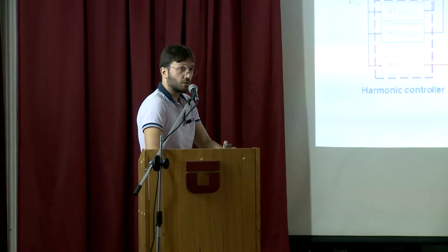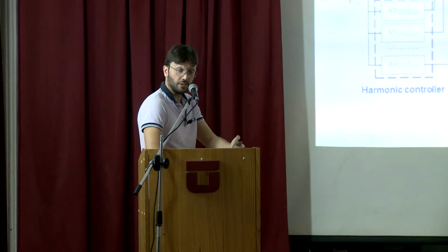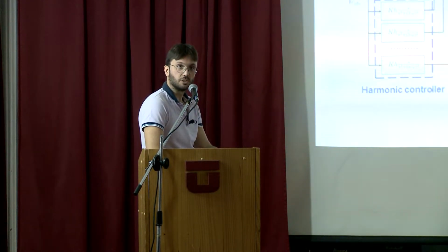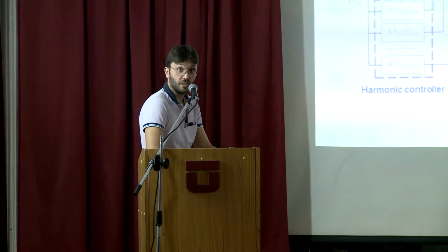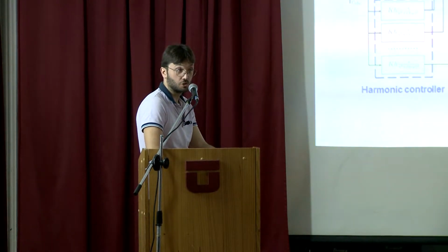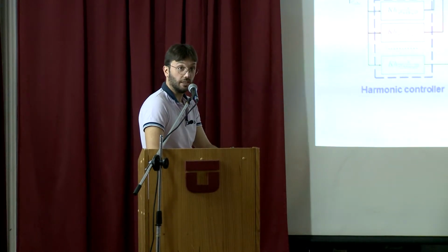So in order to have a nicer waveform, we need to have a capacitor, LC or LCL filter. Capacitor and inductor can resonate, and this is exactly what we saw yesterday: we tried to increase the gain of the voltage controller, but then it started to oscillate.